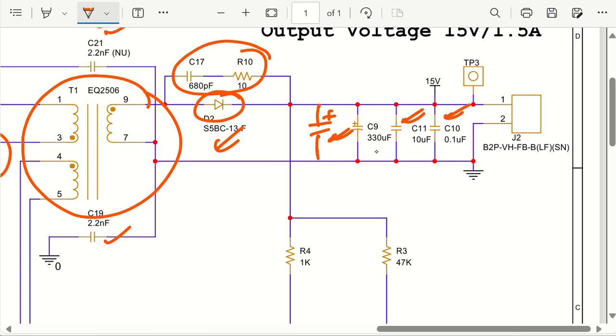However, I have given you a technique for how to calculate the output capacitor value. So 330, you will see that 330 is more than enough. These filter capacitors are actually used to reduce the ESR value. So that's the reason we always try to give 0.1 microfarad or something like that. If you want, you can remove this, make it as DNP.